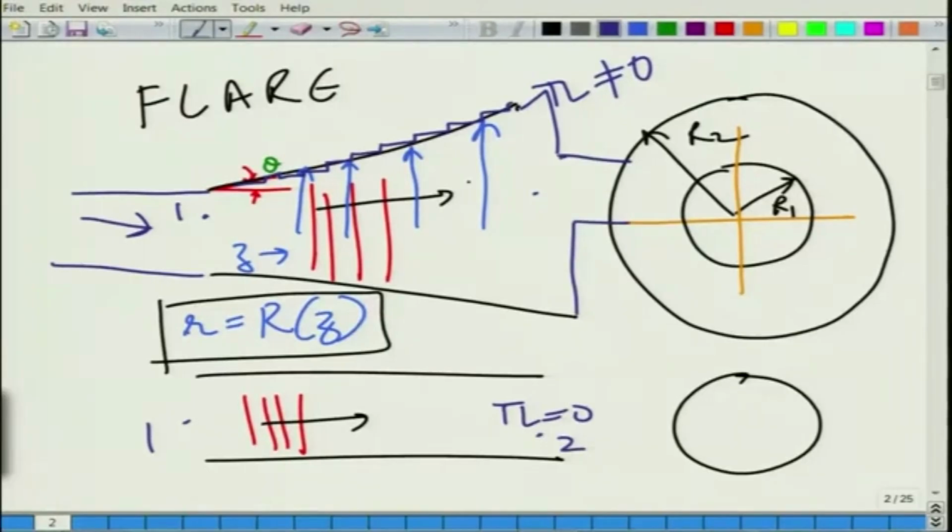So, the real structure will obviously be much more complicated, but the point I am trying to make is that at some parts of the engine you may not have that much space, while at other parts you may have much larger space. So, why not get an optimal profile, based on the space available, manufacturing constraints, and the cost of fabricating such a muffler, which obviously is more than a uniform pipe. And importantly, because of the increased space available as we go towards the outlet, one can do a lot of things inside the muffler.